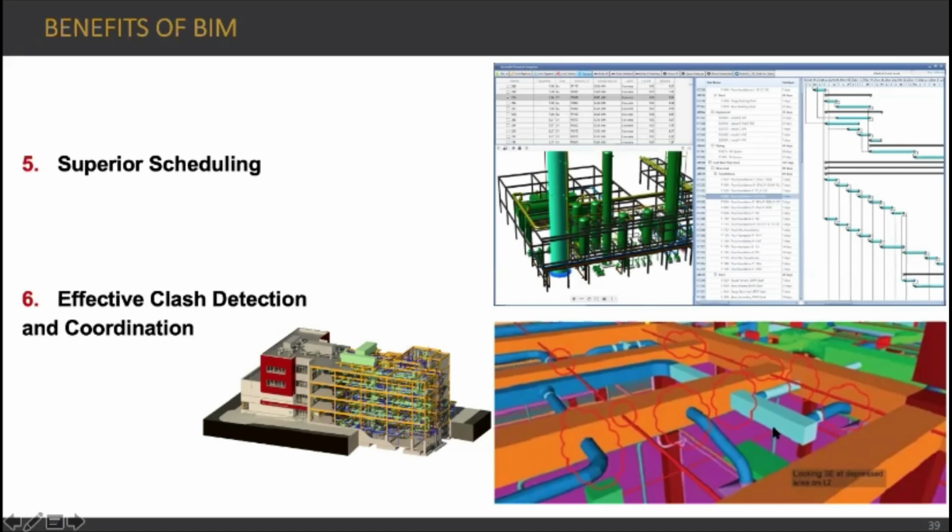And this is called a hard clash. With BIM, if you assign some rules, you can also detect soft clashes. What do we mean by soft clash? It means, for example, this channel may need some space around it. You may need at least 50 centimeters for repair or maintenance purposes after the construction is completed. If it has only 30 centimeters, the program warns you, so it can detect those kinds of soft clashes as well as hard clashes.